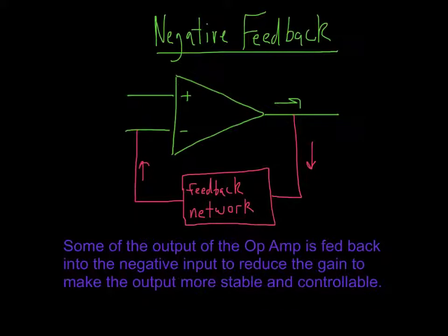or you can use to make a circuit that does math. The point of this, which seems kind of strange, is that you are continually feeding back power into the negative input here so that this thing never hits the rail. You keep it in a very stable regime.